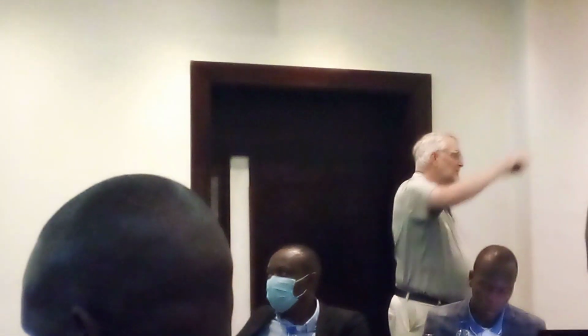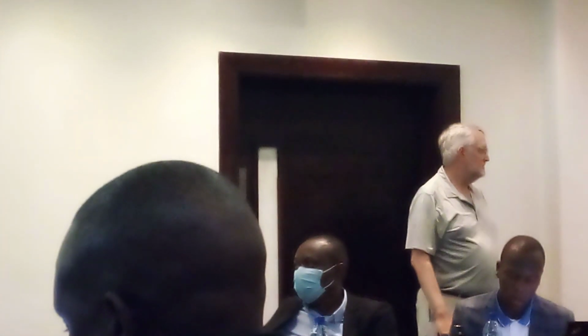Okay? Very, very important. It's something that you guys must please put into your design. I know, well, in my world that I live in Southern Africa, those things normally get stolen if the public have access to the dam. But there are some solutions that you can think of. Even when you have concrete, your concrete dams should have visible block numbering. Even on the outside. So if you look at it, you can see, I have a new seepage point at block number 10. And you should number the blocks.